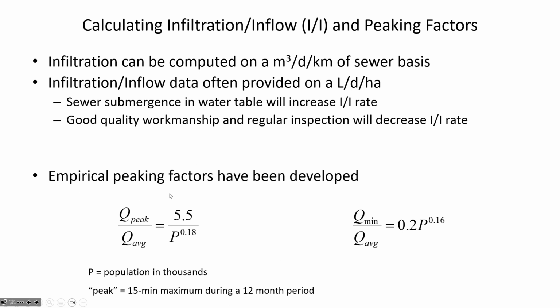And this is kind of similar to an idea that we've talked about before, that in a small town, it may be that people have a more similar schedule, where if you have a small town and it's not very spread out in terms of geography, and people follow about the same hours, then there would be a much larger peaking factor that has to be applied, because the water isn't experiencing what's known as routing.